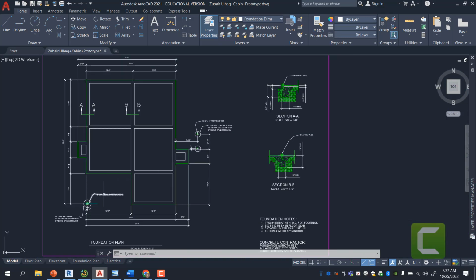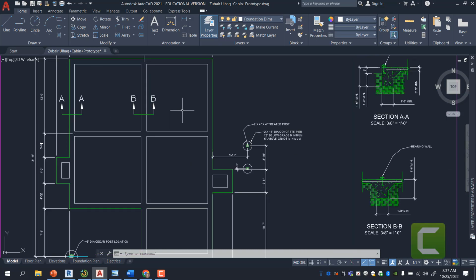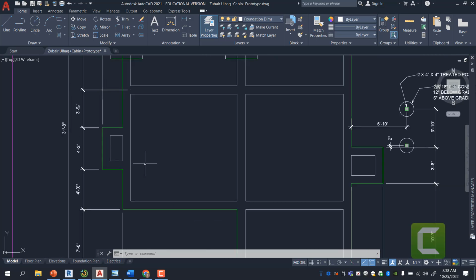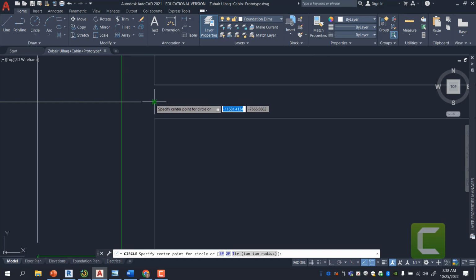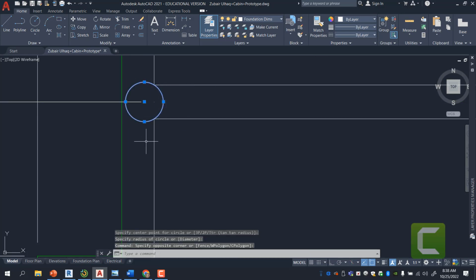Now, on a foundation plan, what you're looking at is the location of all the grade beams, which are indicated by the section A, the outside of the grade beam, and the middle grade beams. Now, if you do have piers, they'll be indicated by a circle that's drawn with a dashed line, and that would indicate that there's a pier.